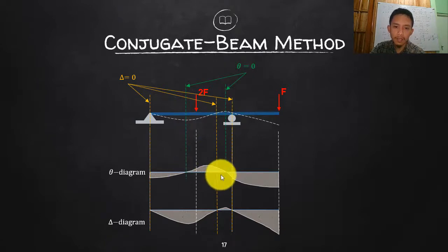Okay, and in here, why is that 0? Because the beam will bend that way and bend up before it goes down. It will not bend up exactly at this one, because that depends on these forces. So again, why is that 0? Because this is the highest point on the elastic curve. So if I draw a tangent line, it is also parallel to the original beam.